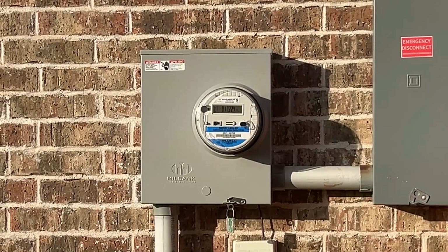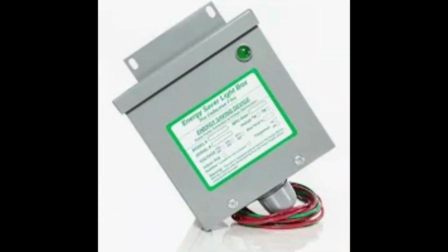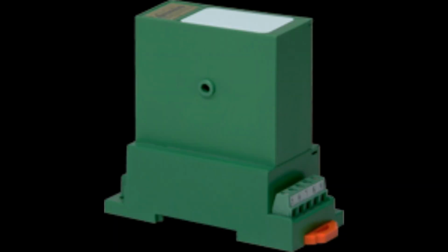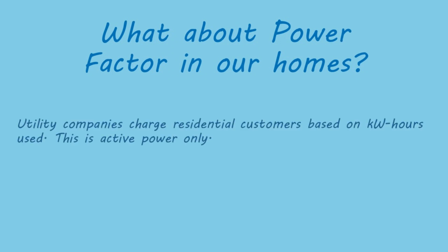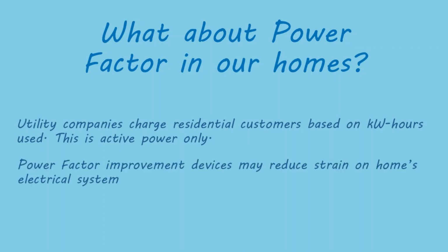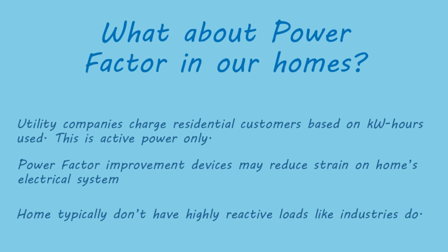So what about these devices that are advertised to improve power factor or lower utility bills for residential customers? Well, they typically don't save you money because utility companies charge residential customers, like I said, just based on kilowatt hours used. So these things might reduce the strain on your electrical system, but they're not going to save you money most of the time. Also, in our homes, we don't have a lot of highly inductive or capacitive loads like industries do, where they've got a lot of pumps and motors and things that cause the power factor to drop significantly. So residential customers typically don't really need to worry about it anyway.